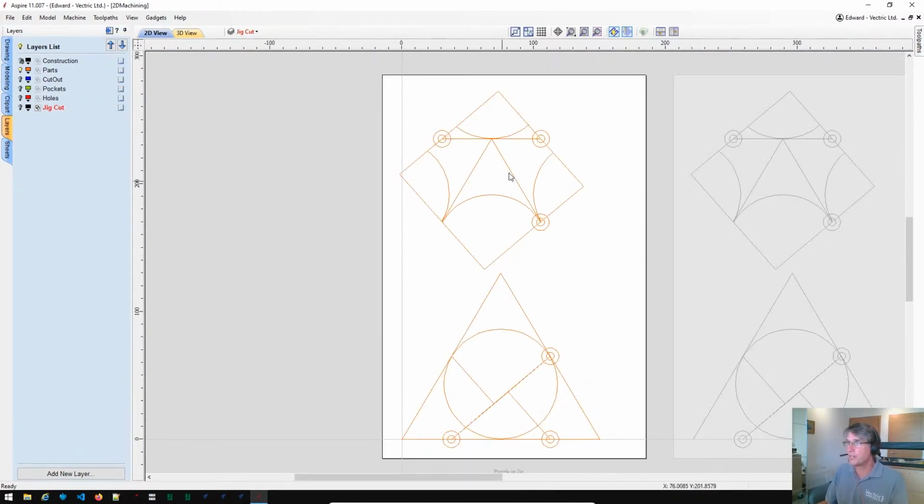Of course, we're only interested for now in identifying the center area here, because all I need to do now is drop a 3D piece of clip art into that area and generate the toolpaths for each one of those bits of clip art, and everything else should then work out. We'll be able to find the XY coordinate by using the bottom corner of the triangle. We're going to set Z off the top surface of the oak puzzle in situ once it's in the jig, and then we're simply going to machine over the surface to carve away a little pattern in each.